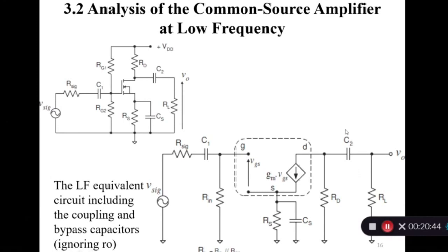Suppose you are sitting on the C2, we are looking for the resistance from this C2, it is RL plus RD. Be careful in the class test, assessment or in the main exam, I will give you some question which is parallel combination. Not every time the series combination. Here in this question, the resistor looking from C2 is RL plus RD in this loop.